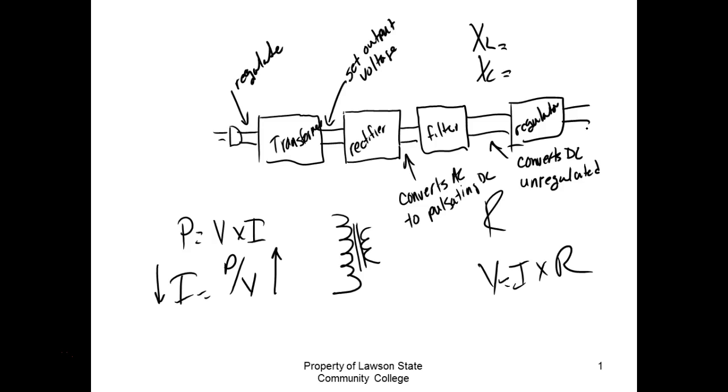If you ever look at the power supplies, it's going to give you what it regulates guaranteed on the input and what it regulates guaranteed on the output. It usually gives you a maximum current. So this is a switching power supply. Somewhere on here it says this guy right here will handle an input anywhere between 100 volts and 240 volts.